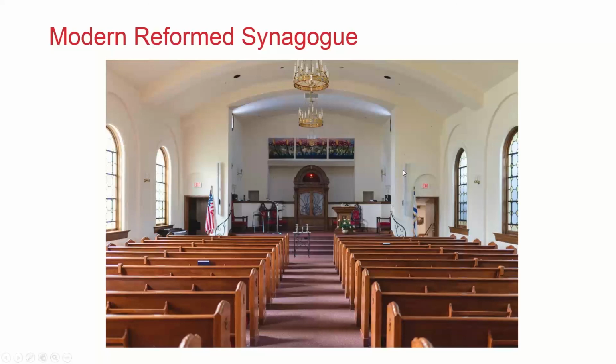You really want to keep the sound low, keep the line arrays, keep the sound away from that curved surface. In this case, we've got a bad reflecting surface, and we're keeping the sound away from it with a line array rather than fixing the surface. It reflects sound and keeps the room reverberant for music and singing, but we keep the speech away from that curved surface.